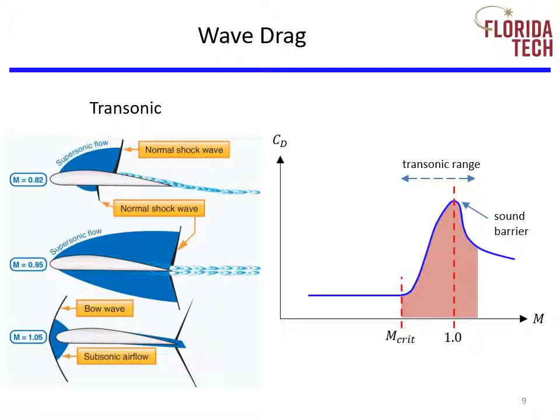We've seen the diagram on the left in a previous module. When the flight velocity is greater than the critical Mach, the drag coefficient increases. Below critical Mach, the low speed polar is fairly unchanged. Critical Mach is where the flow reaches sonic somewhere on the wing and a normal shock wave starts to form. After the critical Mach is exceeded, then a sudden increase in drag coefficient called drag divergence is experienced. Beyond Mach 1, the drag reduces, but not to the level prior to the critical Mach.